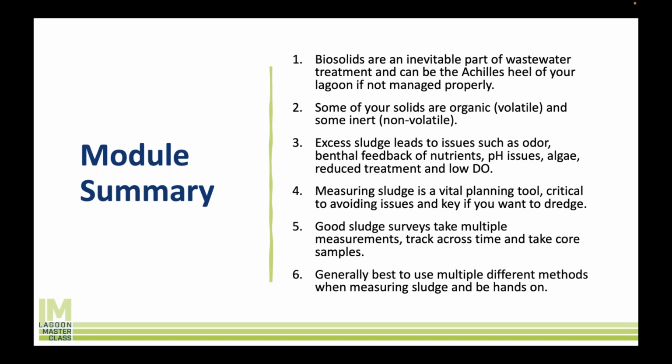Some solids are organic versus non-organic. You really want to understand the difference between the two. Excess sludge leads to odor, benthal feedback, pH issues, algae, reduced treatment, and low DO, all problems you do not want to have. And by the time you have them in a very acute fashion, it's too late. Now you're doing a fire drill trying to figure out how to get sludge out of your lagoon when you don't have the time or money because you didn't plan for it, right?